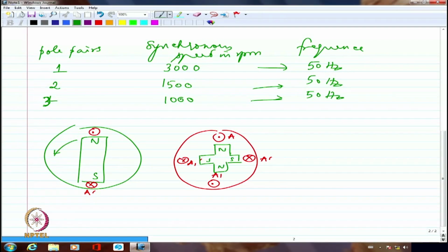So, between this north pole and south pole, although it is a 90-degree displacement, I am actually having a 180-degree traversal as far as the electrical current is concerned. So, essentially the traversal of the electrical degrees is being divided by 2 when I come to the mechanical degrees. This is what I am trying to emphasize.